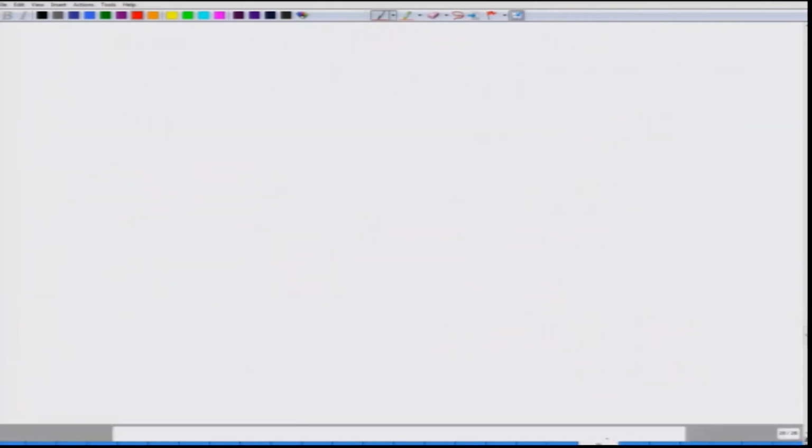Okay. Now, instead of working with free space, which we used just to understand what was happening, we now want to consider what happens through the fiber. Since I am considering the fiber, I know that beta will be some function of omega, correct. But now I am going to assume that my pulse, instead of being just a pulse here, I have actually modulated this pulse onto the carrier, and let me take the carrier frequency as omega 0. Okay. This is how you normally transmit optical pulses.